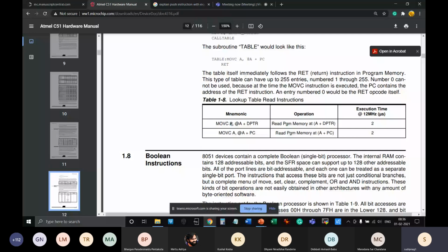That means one instruction is serving multiple purposes. Okay, so it is doing some addition, it is providing address, and then it will do the copy, and whenever the C thing comes, automatically your program store enable signal will get activated, so that your external flash memory or external EEPROM or external EPROM gets read.